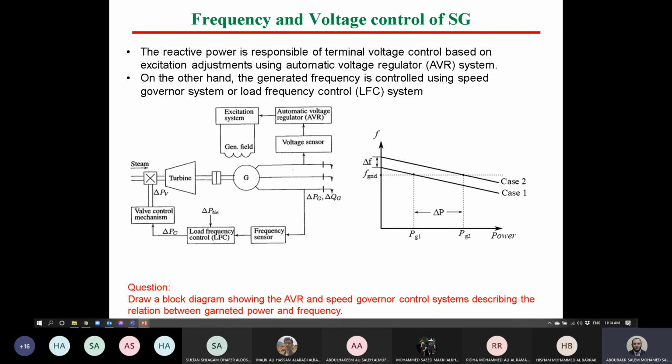We had a laboratory this week, last lab, which is related to synchronizing the synchronous machine to the electrical grid. And we discussed the synchronization condition. If you remember, after connecting the generator to the grid, we started playing with the power of the DC motor, which is the prime mover of the synchronous machine, by means of changing the supply voltage of the DC motor.